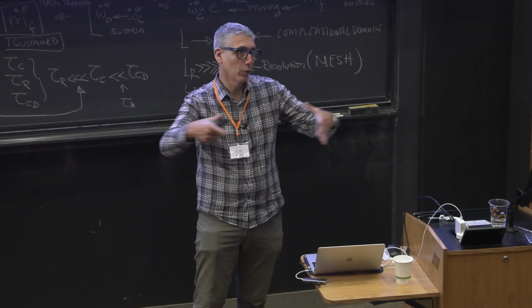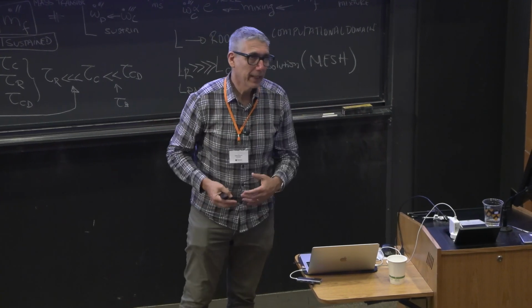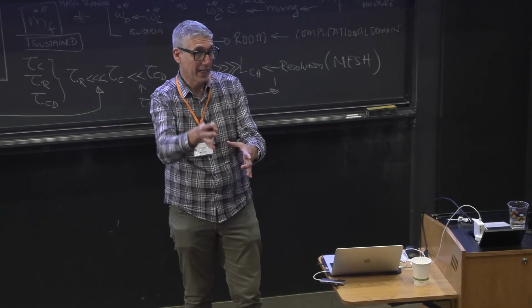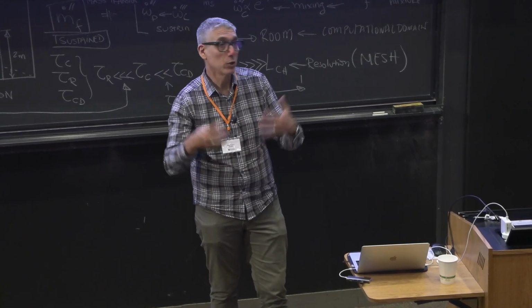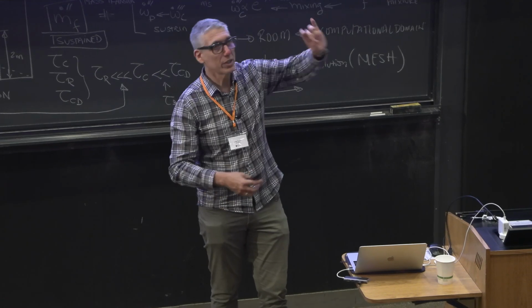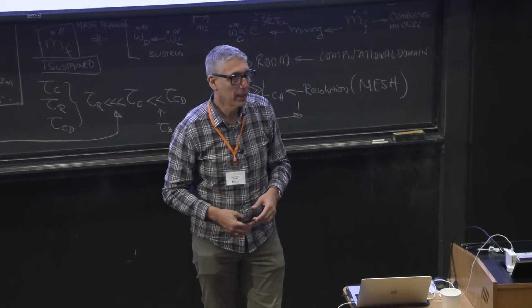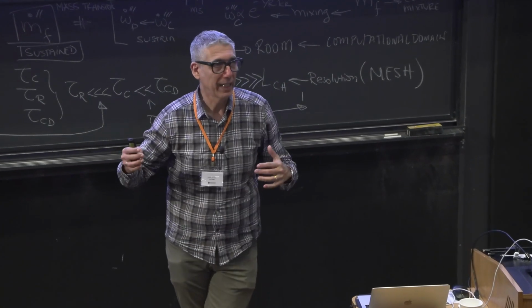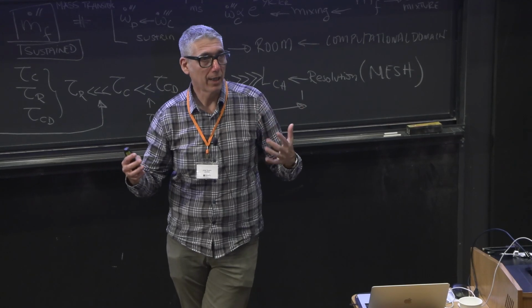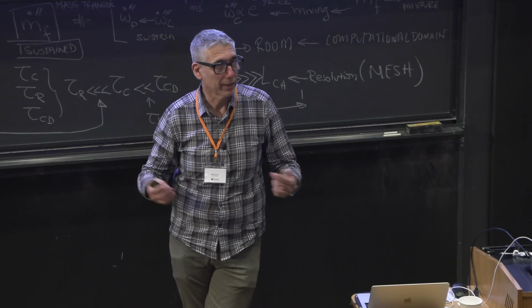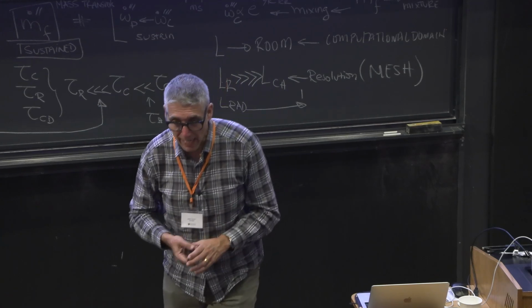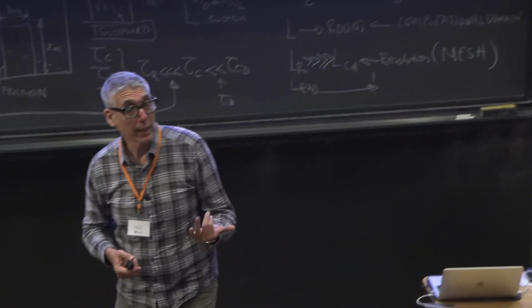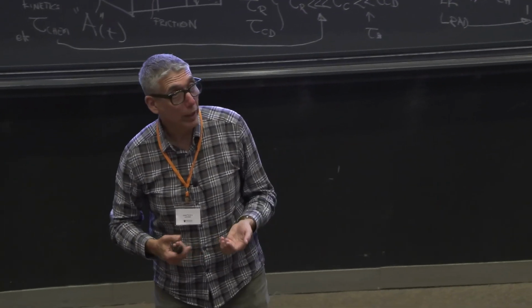That was not a circular fire going radially. It was obstructed on the one side, so your entrainment coefficient was not 0.2, and it was not adiabatic. You were losing smoke through the door. So there are all sorts of different components that are exceptionally conservative, but that nevertheless allow me to make a calculation that gives me the value that I'm looking for.